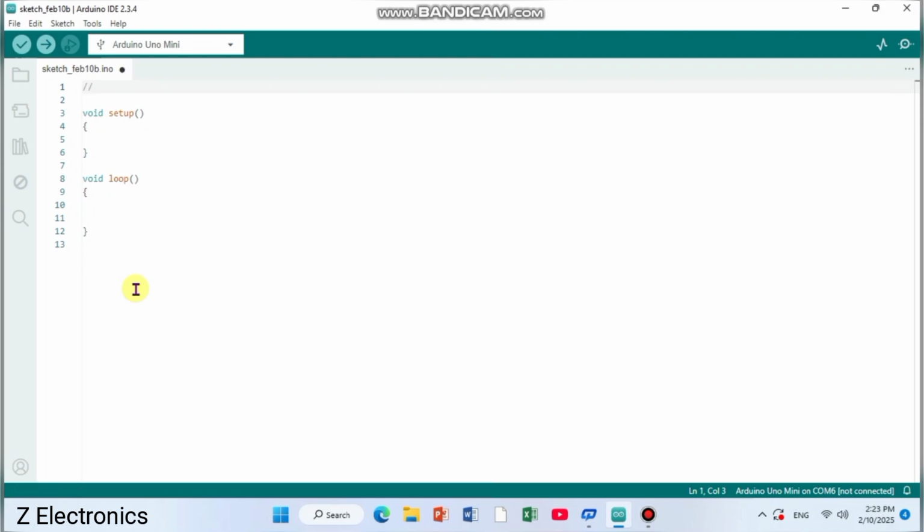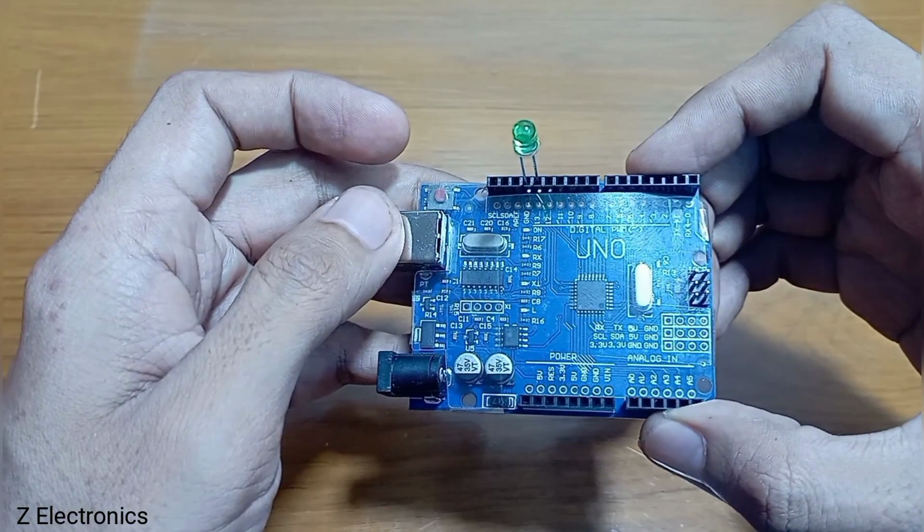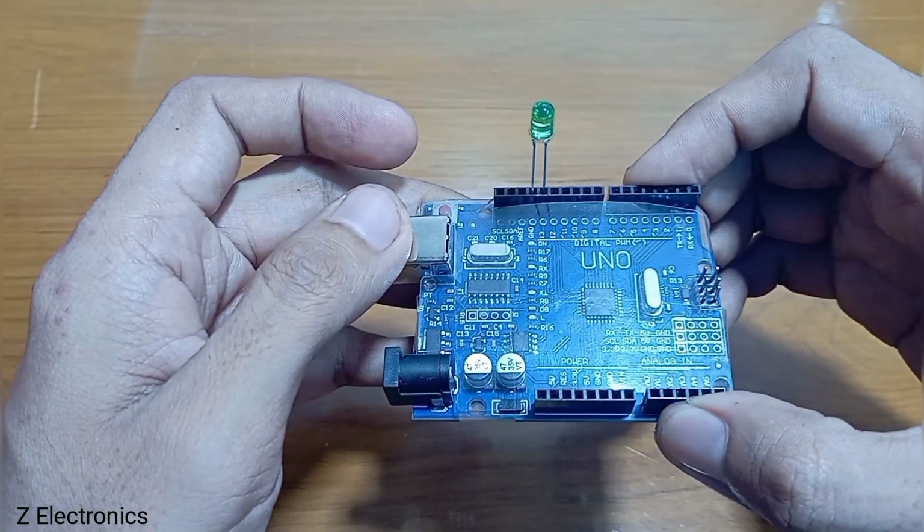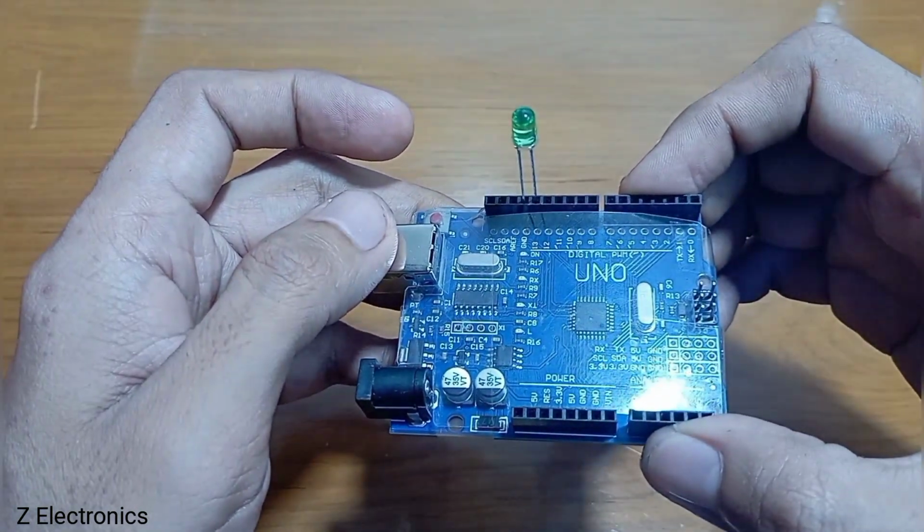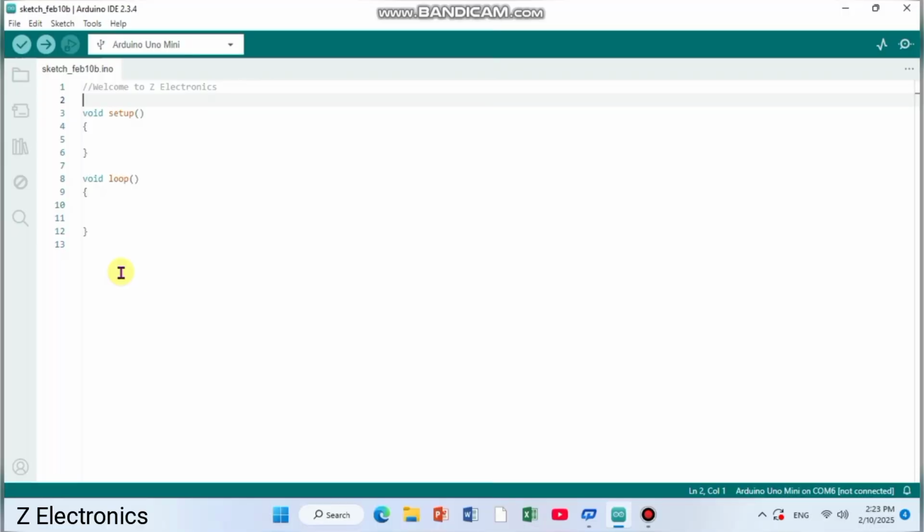In Arduino, for commenting we use //. It tells you the syntax. So as you see in the connection, we have connected one LED to pin number 13. Many people will not use a declaration. But my opinion is, if you use a lot of devices or components, it will be a bit confusing not knowing what other things we have used in our program or project. So it's better to practice the declaration part.